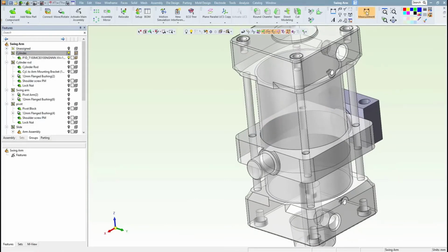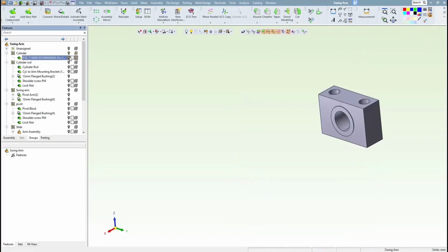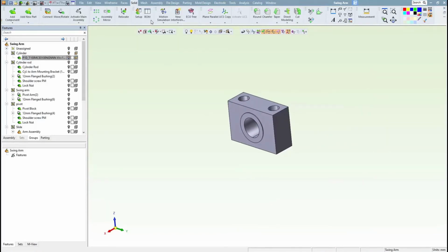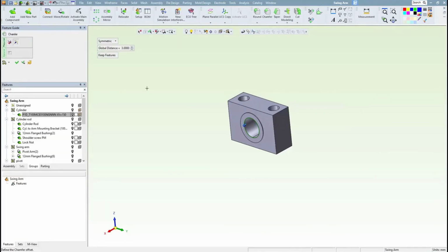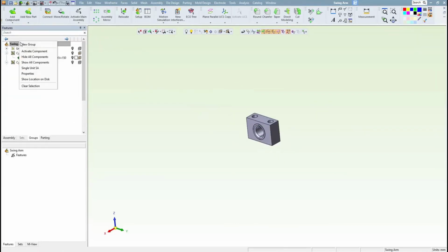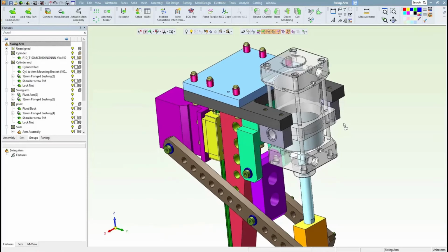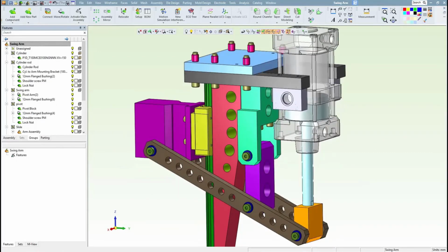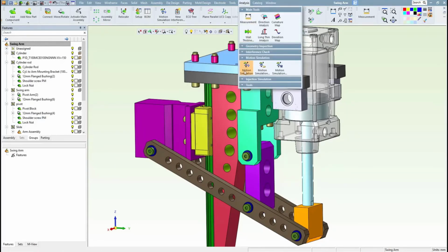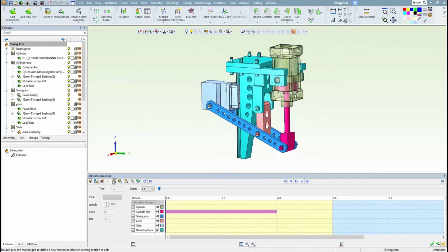The problem in this case is pretty simple. Some of these parts are standard components from step files, and the round on the cylinder pivot is colliding with the bushing block. I'll have to add a chamfer on the block to take care of the problem. Now the design checks out okay. With no initial interference problem, I should be good to go for calculation.